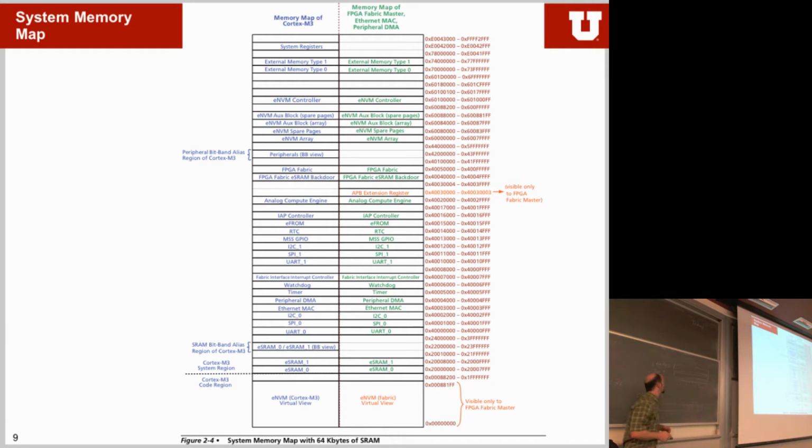And what happens is, if you want to clear one of these bits in this register, you write into this memory location and set the bits here. And then only the bits that you actually set in here will be cleared in here. So setting would mean you write a 1 in here, and then you make sure that this bit would, for example, be cleared. Or if you do it this way, so you set 0, 1, and the rest all zeros, then you would make sure that this bit will be cleared to 0 in the actual register. If you want to set a bit, you could use a second register.